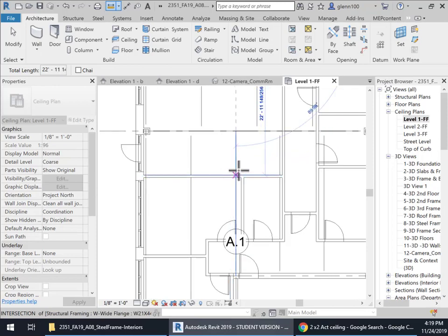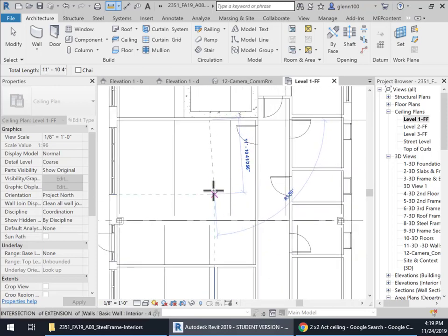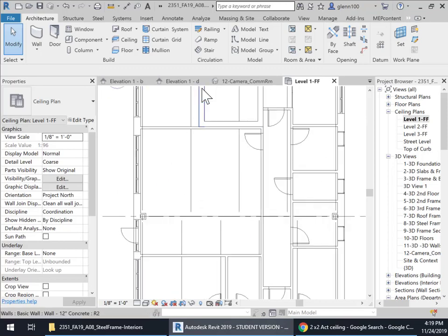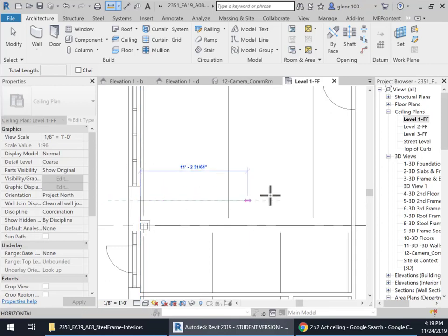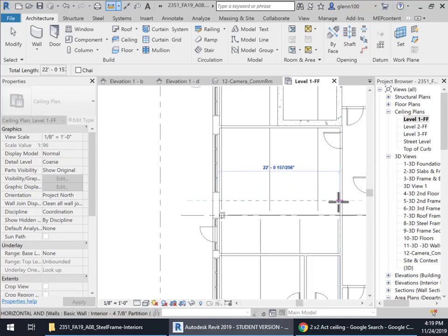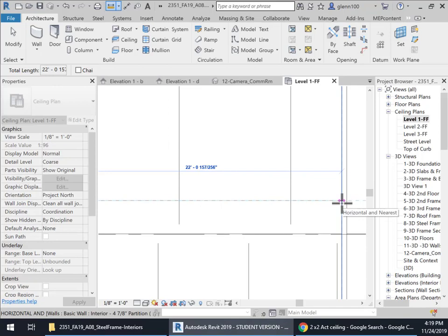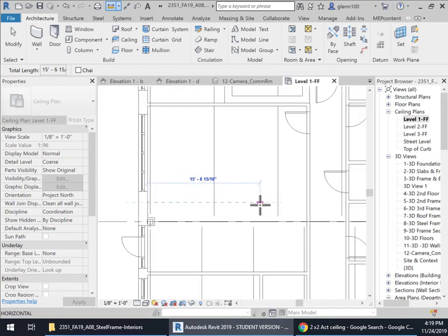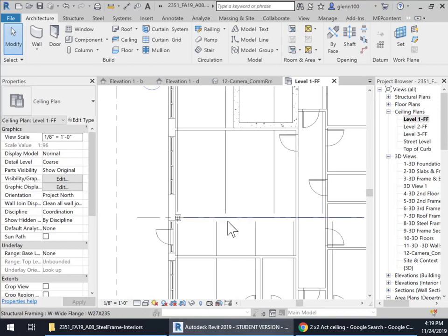That means if I do a 2x2, I'm going to have either an extra foot on one side or an extra 6 inches, if I want to center it. Let's take a measurement across the other direction, get an idea here, and that is, for all practical purposes, 22 feet. The difference we can make up in trim. So we've got an even 11 panels across and 11 and a half panels in this direction. And so we'll just keep that in mind as we go to adjust this.